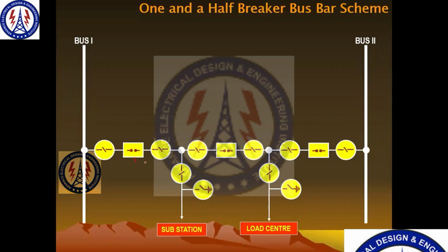So this one circuit breaker, this one circuit breaker, and this. So we have connected this one circuit breaker along with sectionalizer, if you remember, of bus 1. So we have connected this small part, isolator, circuit breaker, isolator between these two feeders at a strategic location. Okay, not anywhere, but in between the line isolator and circuit breaker isolator.